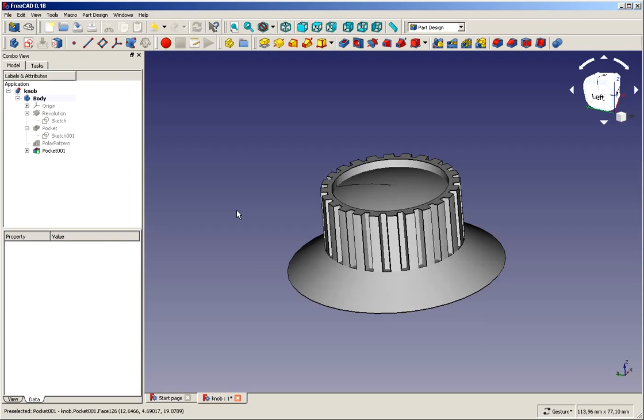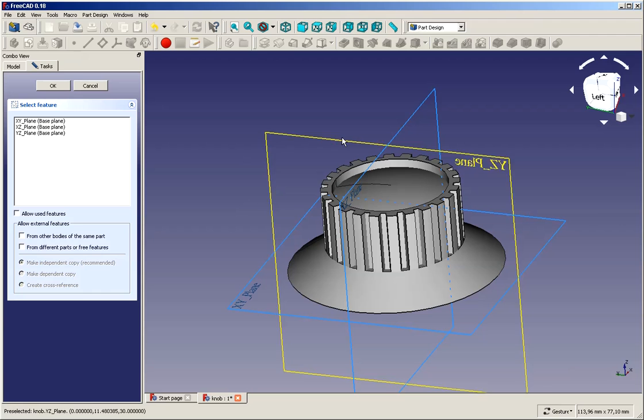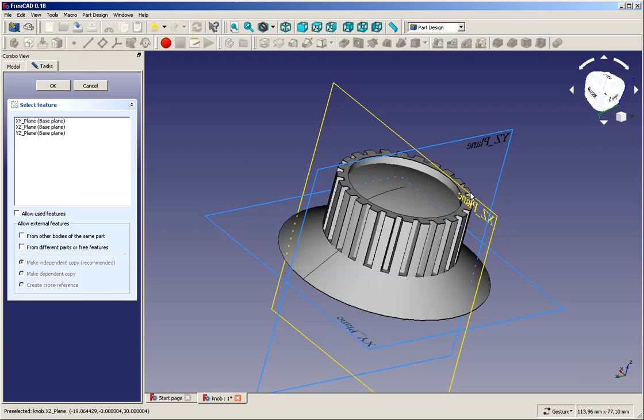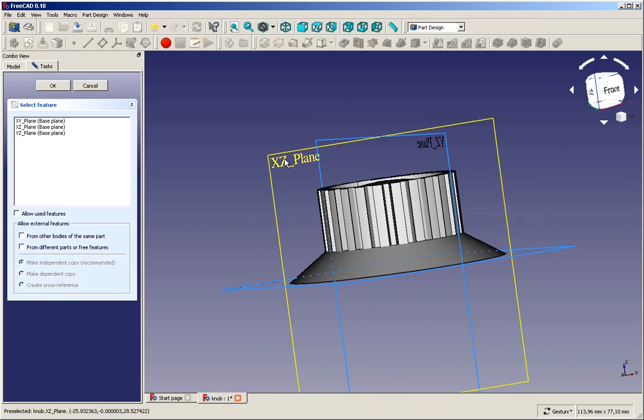So this is what we need for this hole, and the next thing is we need a hole for the screw and a hole for our rectangular nut that holds the screw. We will put this also onto the sketch for this hole, but first let's create the hole for the screw. Again, we don't need any fancy things like datum planes or such. We can simply create a sketch, and we this time create the sketch on the XZ plane.